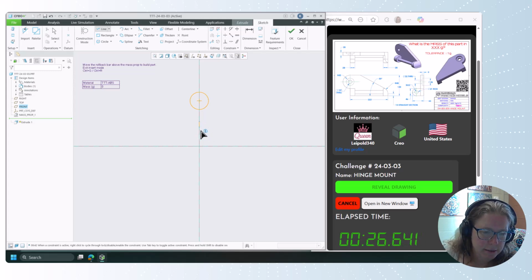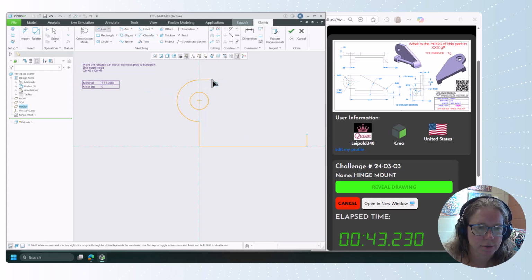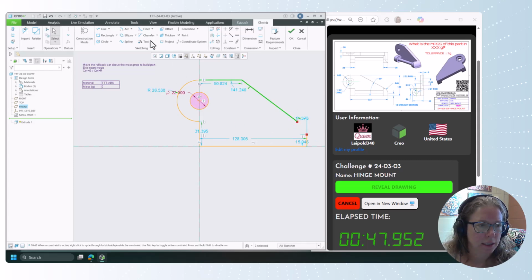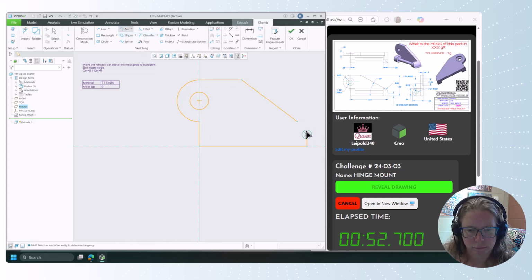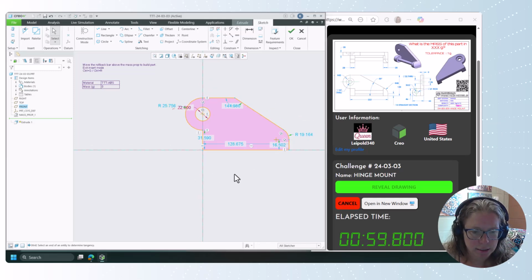Let's add some lines. And let's see here. Let's add a center end arc. Let's come down here, like that. And then we'll use L this time to grab our line tool, and our arc tool. I can select that line, and the pop-up lets me select tangent.